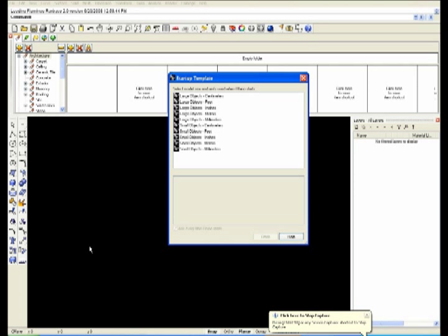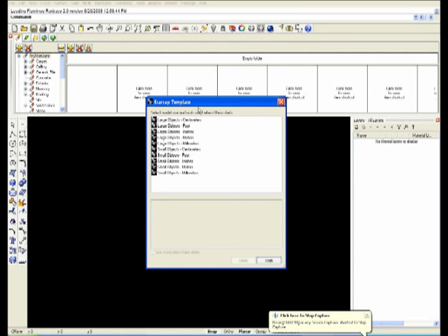This program is a 3D modeling program, and in this section we are going to use the option large objects centimeters. That way we can build our small model and you guys can see it better. So in our case, large objects centimeters is going to mean that every square on the grid is going to be 1 centimeter. Okay, so keep that in mind.